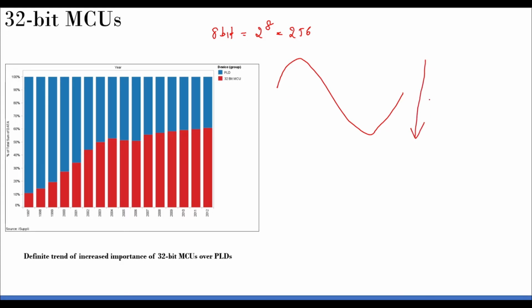So this is the entire dynamic range of the waveform. You are going to divide this into smaller groups. Let's say V is your original total range, this is V up, and then you are dividing it by 256. So delta V is given by this, and this is actually delta V. So the resolution is like V by 256.